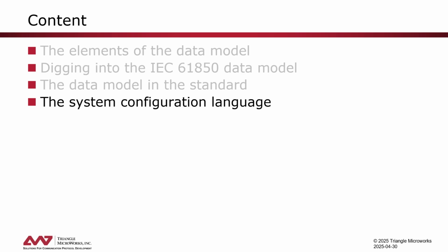Okay, we didn't discuss the substitution in detail in this webinar, but basically the way substitution works in IEC 61850 is that you have attributes where an operator can write the value he wants to substitute. As an example, if we lose the position information from a switch, and we know that the switch is closed, we can write that value there. And then there is another attribute that we use to enable the substitution. Once we enable the substitution, so we write true into that attribute after we have written the value that we want to have,